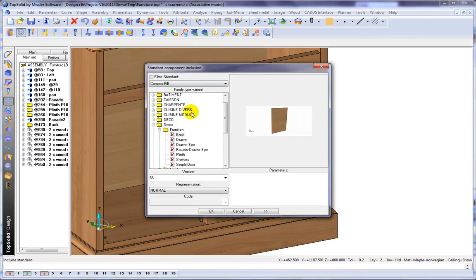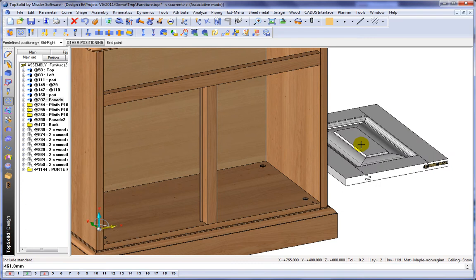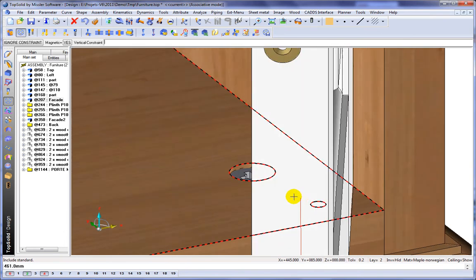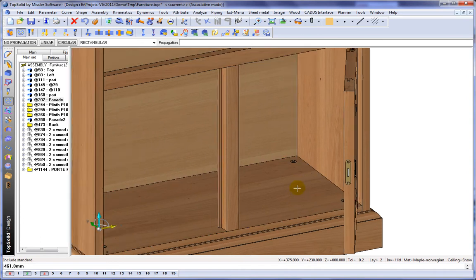And now here, let's add some more components. How about we start with a door? So here what we're going to do is measure from there to there, give it a little clearance, and yes, we're relating this parametrically, and we'll measure again that length plus a little clearance, or I should say minus a little clearance. We'll locate our design. We want a right-hand door, and basically what we want to do is locate it right there. And like that, our door is inserted.